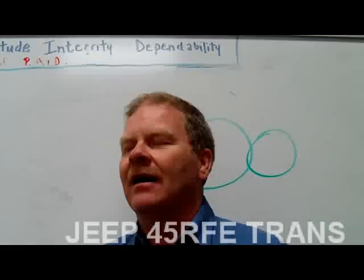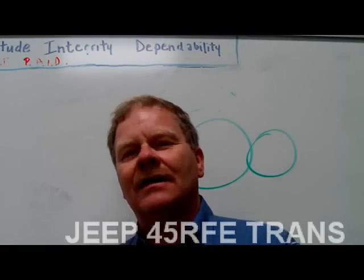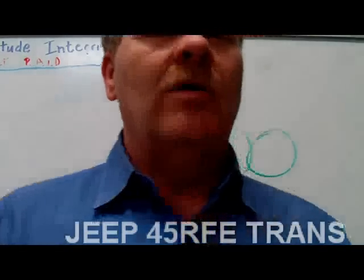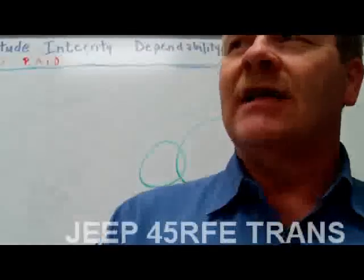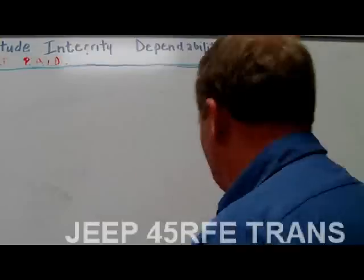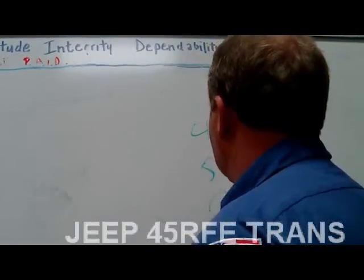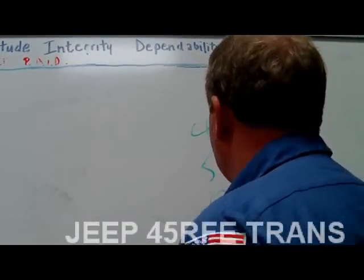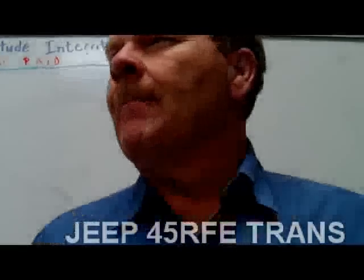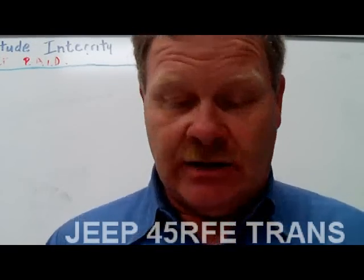See, it's got feedback. It knows what it's doing. It knows that if the gear ratio is not right, that clutch may be slipping a little bit. It says, I'm going to put a little more fluid pressure in there, and I'm going to record that so that whenever my technician plugs his scan tool in, you may see clutch volume indexes that look like 40, 50, 70, and 150. If you've got one that's really high like that, you know that clutch is slipping. Do you have to be driving it when you're doing it? No. It's in the memory. It just keeps it there. So when you plug the scan tool in, you can go in there and test.